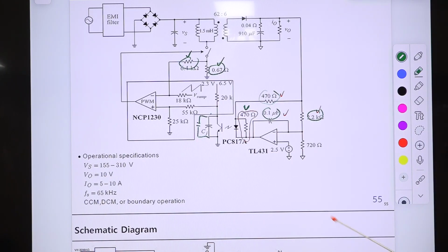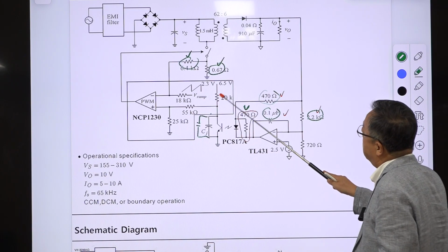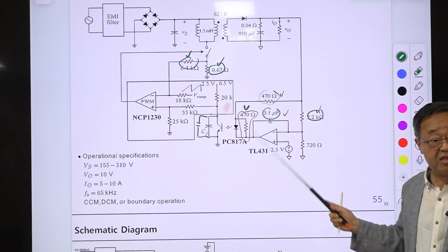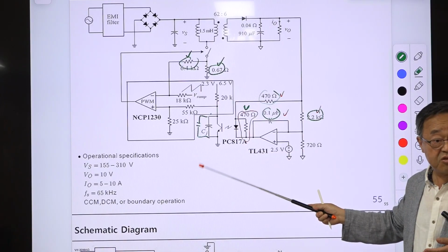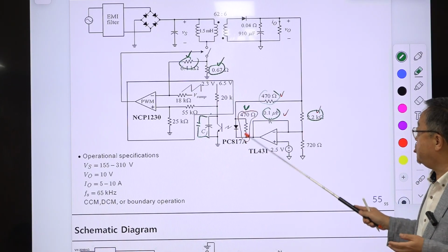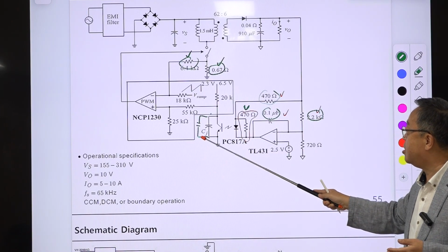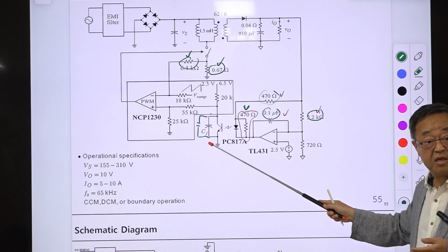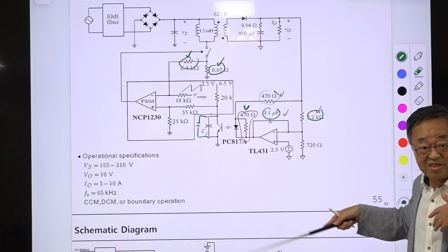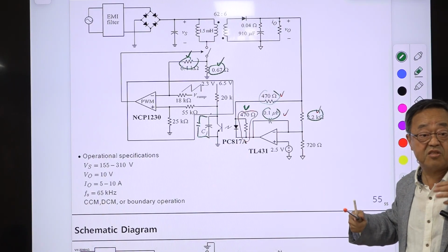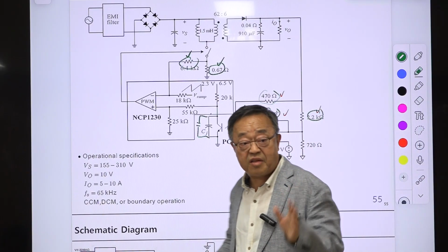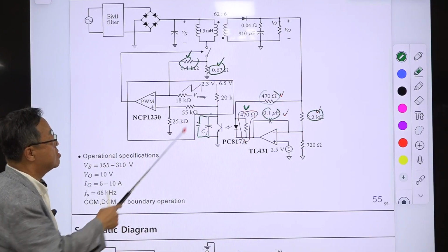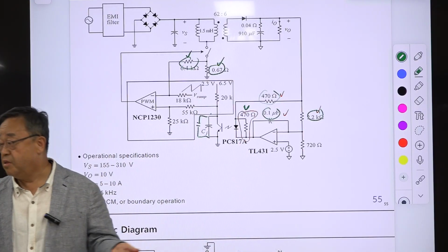The same goal can be achieved by increasing these capacitance, these resistance, but they are fixed by this NCP something. So you cannot change this. You should change this, and you need some additional capacitance. Okay, but you cannot reduce this. You can increase. You can add something in parallel, but you cannot reduce this. So there is some limitation because of these values. Right?